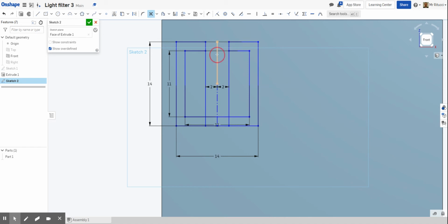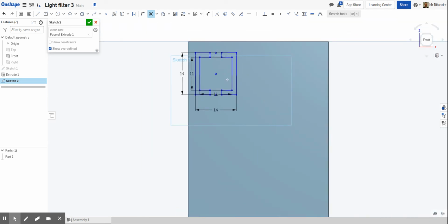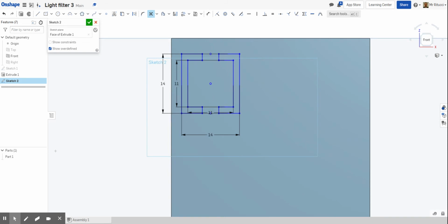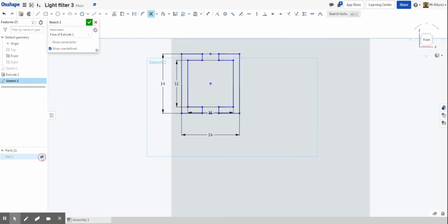Okay, you can create any pattern you want, but what you've got to think about is what the laser cutter will cut out, and what will be kept and what will be left. The tendency sometimes for students is not to think about the laser beam cutting the plastic out and just create a shape, and you're sometimes left with a shape you're not expecting. So just be mindful of that when you are creating a shape. What I'm going to do now, so you can see easier, I'm just going to take away the background so I can see what we're doing, take it to highlight the part.